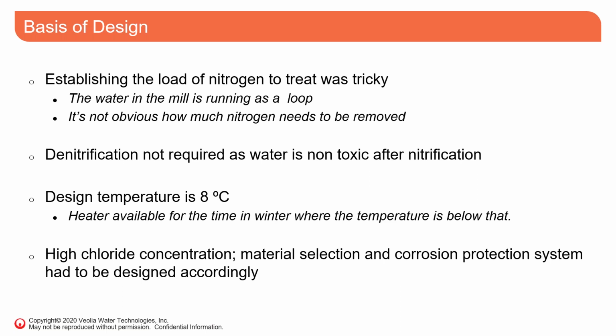Design temperature was fixed at 8 degrees Celsius, so there was addition of a water heater to make sure that we can operate during winter. And there's a high chloride concentration, so material selection and corrosion protection were very important in that application, to protect every piece of equipment from corrosion.